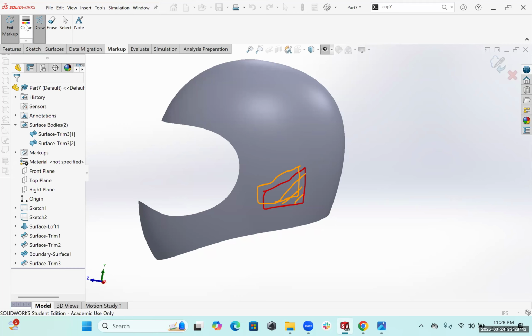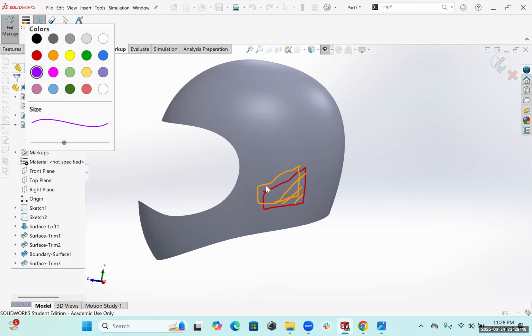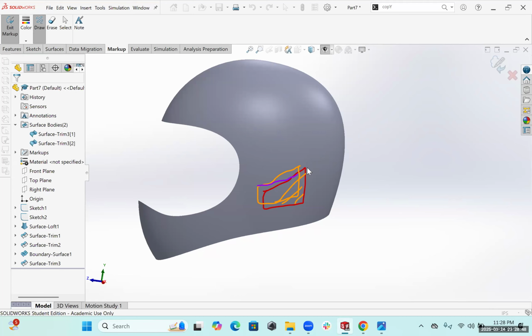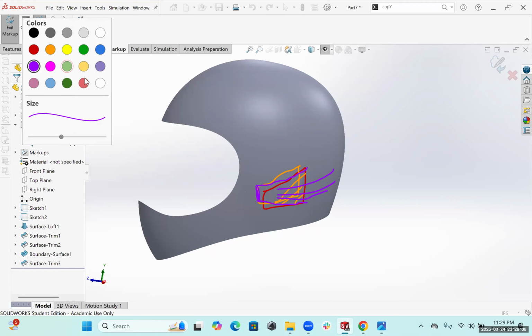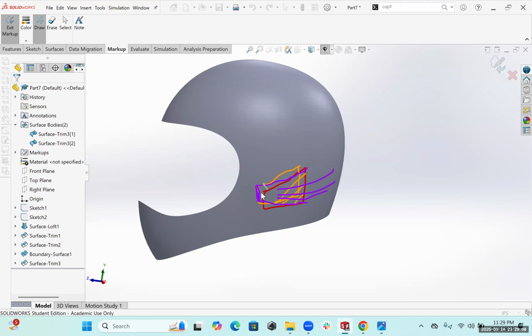Then we're going to come in, add a few guide curves connecting this and this over here, and basically create a smooth surface coming in, ending over here. Once we have the smooth surface built, then these edges will be just a pretty easy boundary connections. Okay, it might not look so clear here, but we'll go through each step and you will see what is the plan.